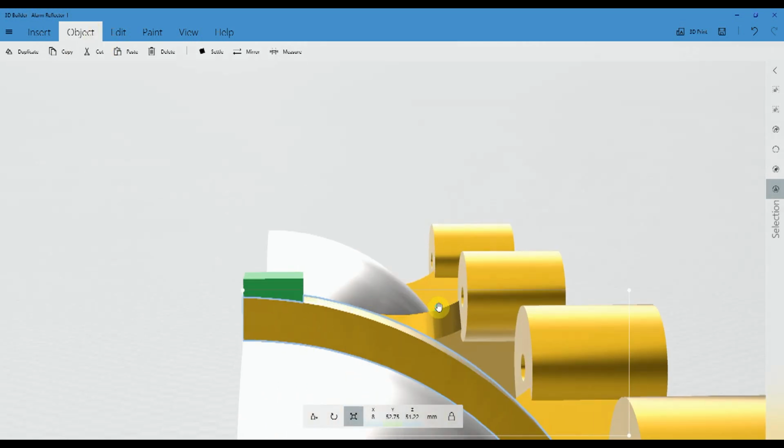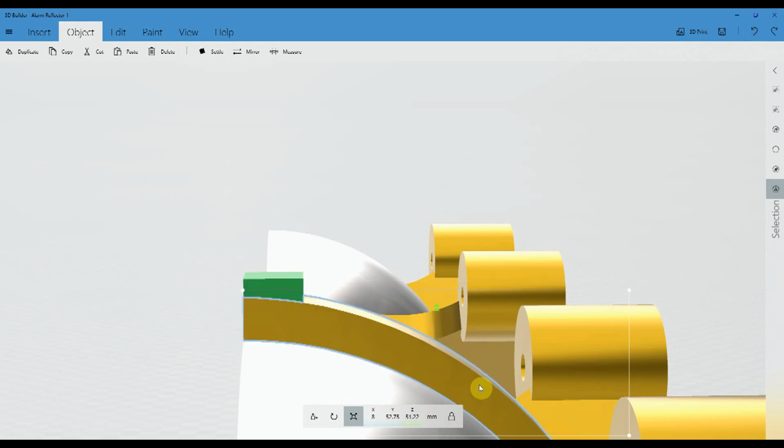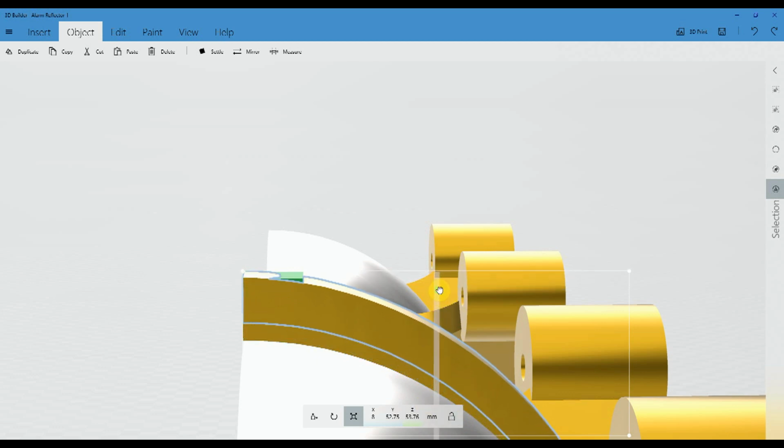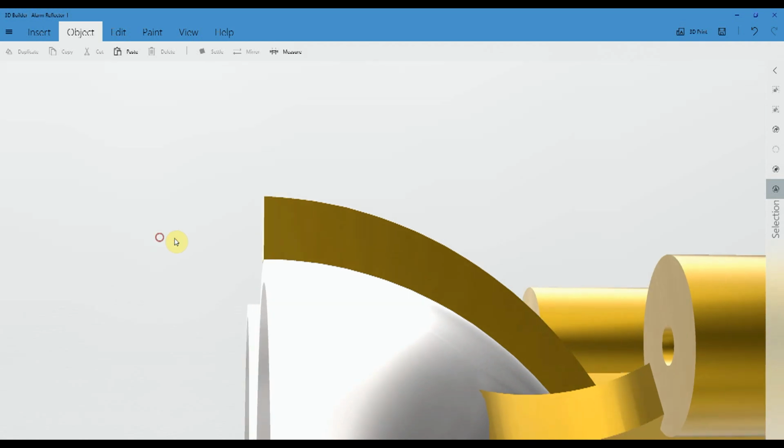Now what I've realized is I can do a duplicate, and then look, I forgot to unpadlock it, and I just increased the Z. So now I've got a perfect curve which the 3D printer will quite happily print from the right hand side, if you see what I mean. I can now delete that green bit, and it leaves me with the area that I need.